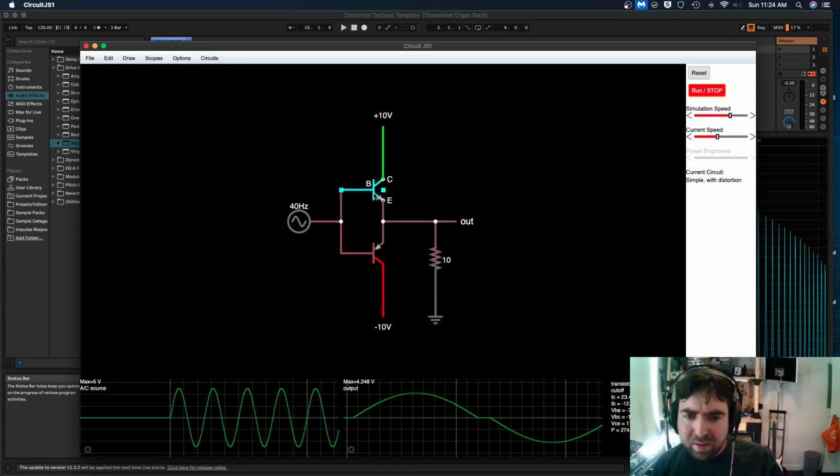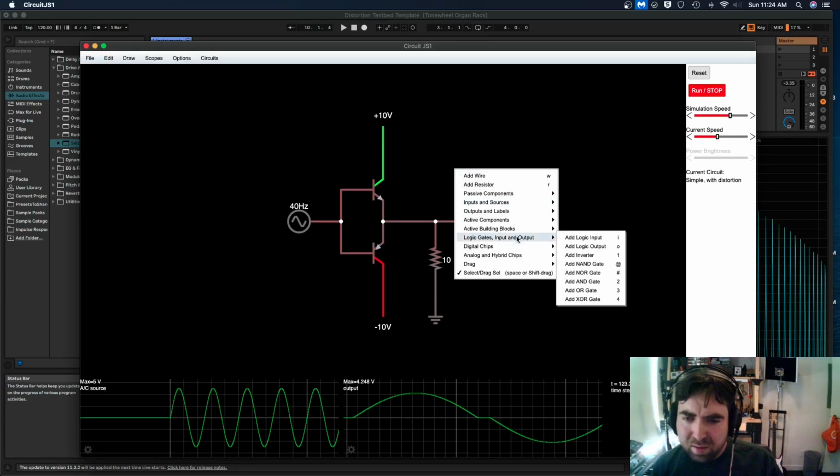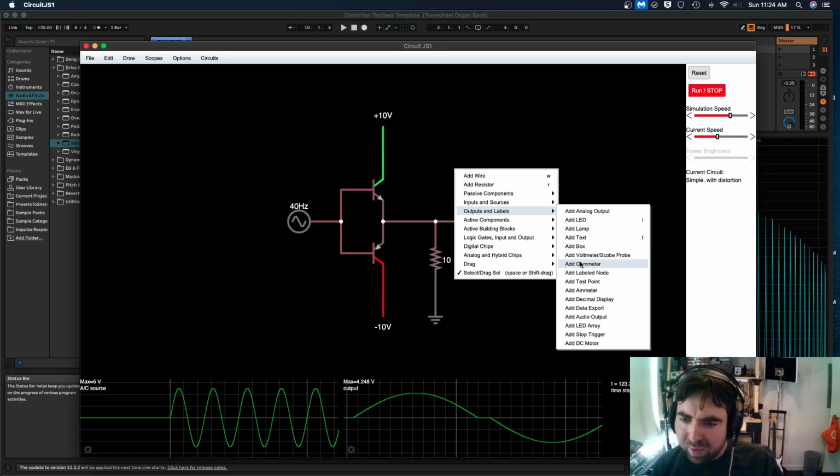and it's because there's actually a junction voltage drop between the base and emitter here and the base and emitter here. If it's silicon, this is going to be about 0.7 volts. For a germanium transistor, I think it's 0.4. We can actually measure this and see what the simulation's coming up with.